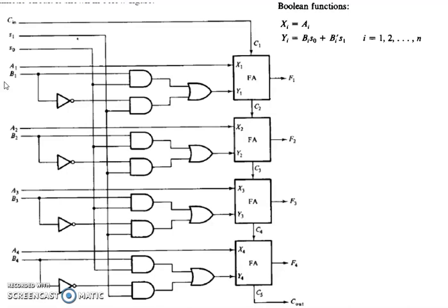We make use of a K-map method to decide which gates or circuits are used to give an input to the full adder in place of this Y1. So if there are n bits, n full adders will be arranged in cascaded form to implement this arithmetic circuit.